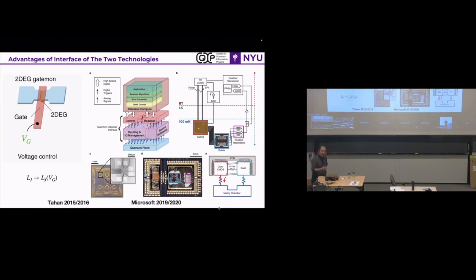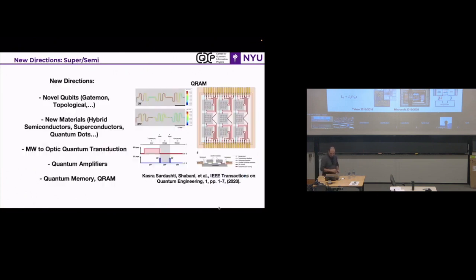And the other thing is that because we have these semiconductors that we are adding the superconductor to, I can go back to CMOS and propose this question: okay, I have my qubit system out there. Can I make my control motherboard cold? Because if it's all semiconductors, can I do the standard processor that we do for a motherboard and put it next to my qubit circuit, and see if they can control each other and just give me the final answer rather than setting the IOs? But these are a bit futuristic questions, I guess. If it's working, we will pay anything to get it, right? We don't have to do this. Having this kind of switch, the Josephson field effect transistor is a good switch.